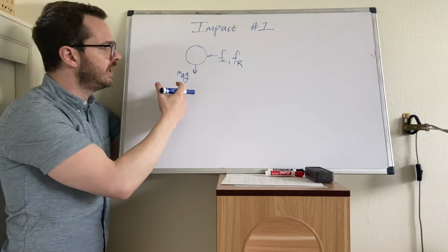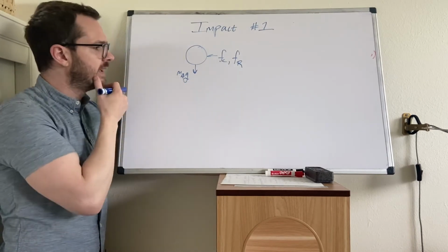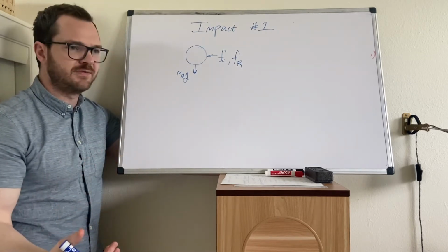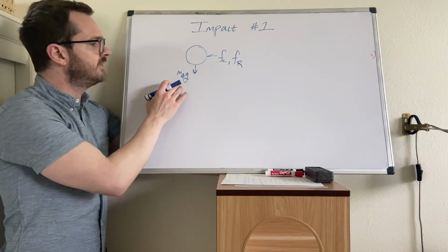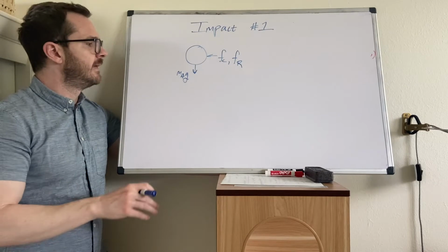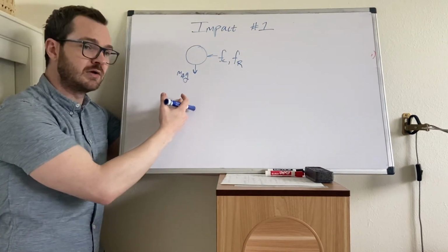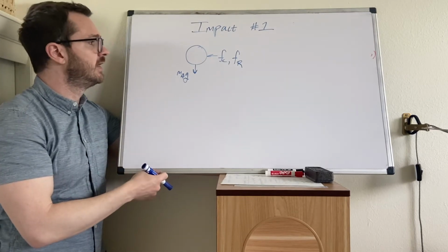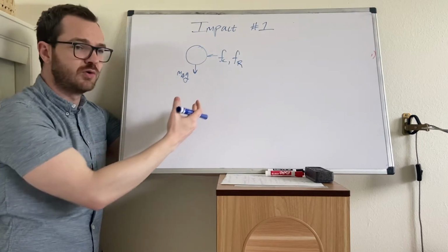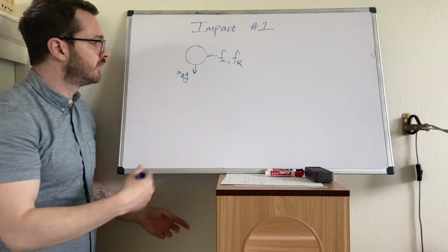However, the impact window, the time of those impacts, is very small. So if the impact only takes place for milliseconds, then gravity doesn't have a significant effect on the ball in that time period. Again, this analysis can become much more complicated, and you can absolutely include this in your impact analysis. For this class, let's ignore it, and let's just say that its contribution is very small, so we're not concerned with it.